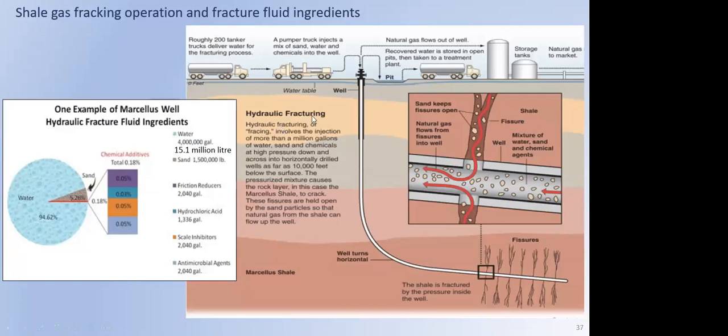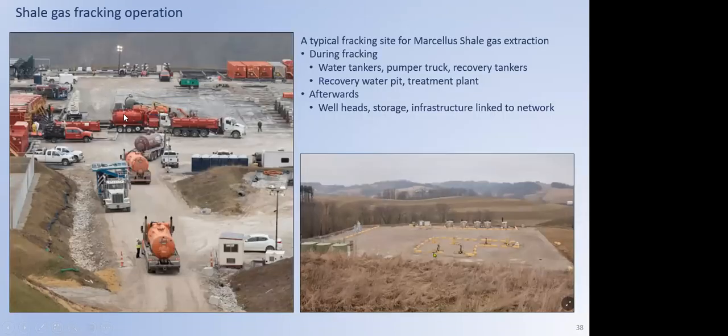Pushing for time, I mean, fracturing. Once you've drilled a well, you would go back and induce these fractures. You would pump in a fracturing fluid, and this happens with a pumper truck at high pressures, and you open up the fractures, the fissures, and you fill them with this hydraulic fluid. You do require a fair bit of water. I'll look at that just now. Those cracks, those fissures remain open, and that frees the gas to come to surface.